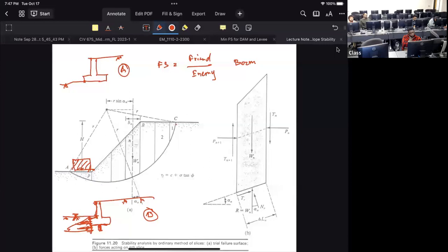Earth pressure is a very interesting theory for soil. Soil has three conditions. One is the at-rest condition: soil is in place, it's not moving, so you have no imbalance. Versus the active condition, which means you take some load out from the soil. If the structure is moving away, then the soil is not going to push as hard.